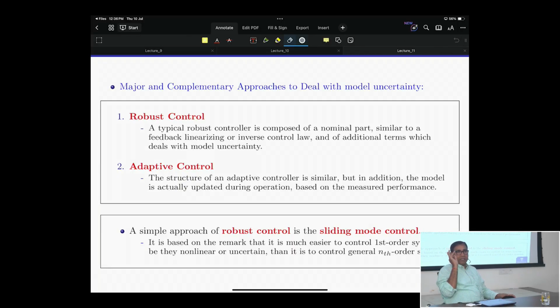Robust control, always remember, there is another misconception. There is nothing like robust control. Always remember these things. A controller which has got the robust properties is a robust control. Up to what degree that robustness is there, that depends, will define, right? Although we say roughly that this is the robust control design, mixed sensitivity design, mixed integer programming design, that's fine. But essentially, there is nothing like robust control. We have to see whether that control is robust or not. Sliding mode controller is one of the robust controllers.